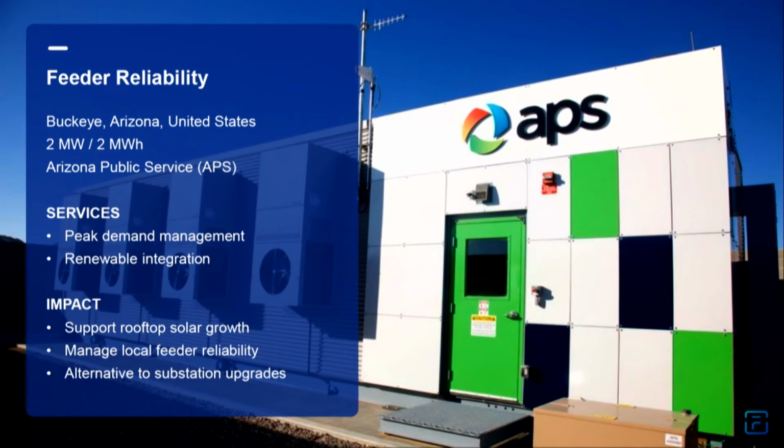Again, one example, real world from Arizona Public Service. They deployed two 2-megawatt systems in their grid, an area of very high penetration of rooftop solar. One of the systems sits at a substation, the second out on a feeder, and they're essentially coordinating the energy storage and the solar to help mitigate some of those reliability issues and avoid the need to upgrade infrastructure.